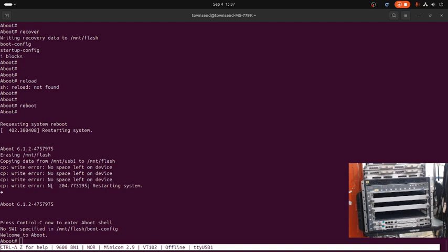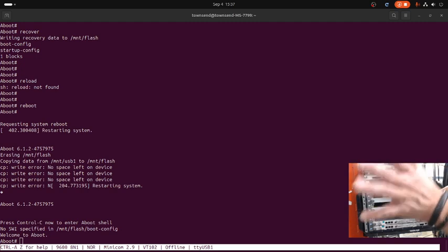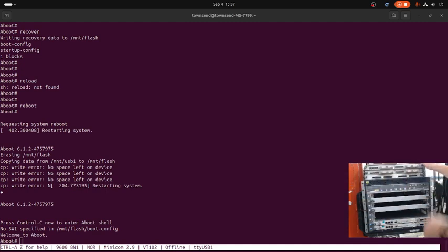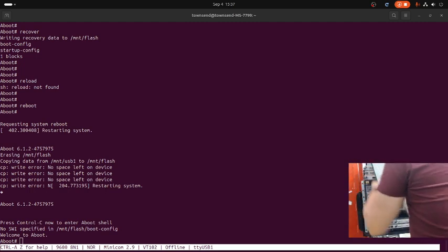So right there we have the chassis, guys. So this is the line card right here. So I will insert these line cards based on the configuration that we already discussed, right? So the MPC4E goes into slot number 5, or MPC 5 right there. So let's insert the module.